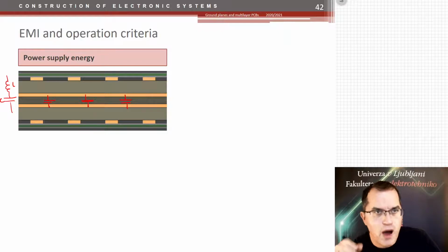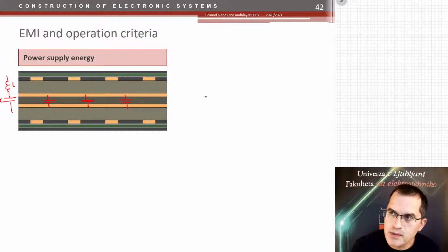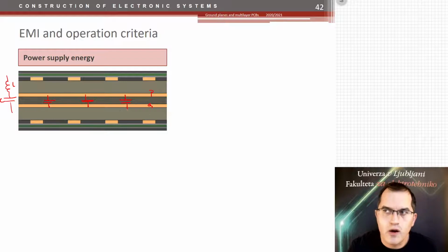So no power at these high frequencies would come from capacitors whatsoever, because they would just not work at these frequencies anymore. So please keep in mind that power and ground layers, or continuous layers, should be kept together as close as possible to maximize the capacitance of these two layers, and that would deliver the highest quality power to the microcontroller and to the digital circuitry.